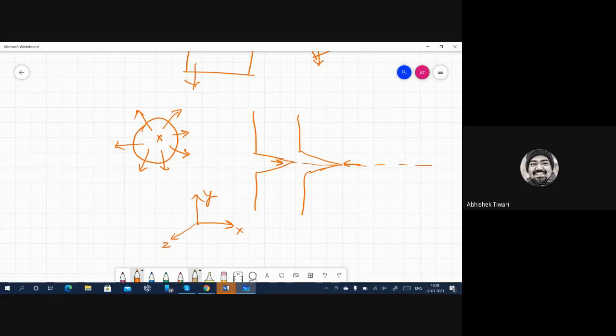So in the x direction, the direction of thickness, you have zero stress at the surface because that's the surface. So how is the stress profile? Stress profile will be like this. At the surface, you have zero stress, and as you go towards the center, you have the maximum there. This is happening in the x direction. So that is the profile of sigma xx.